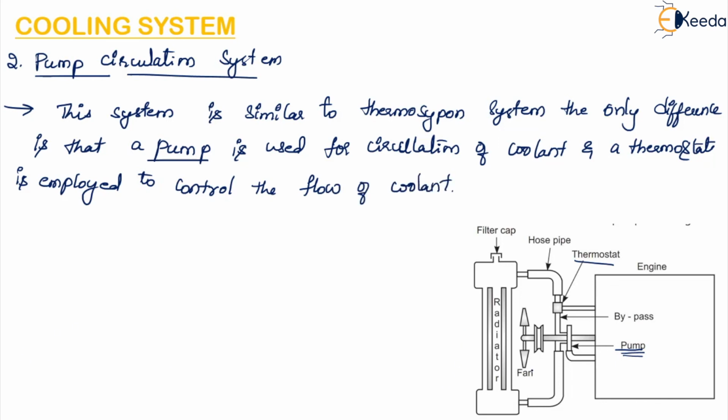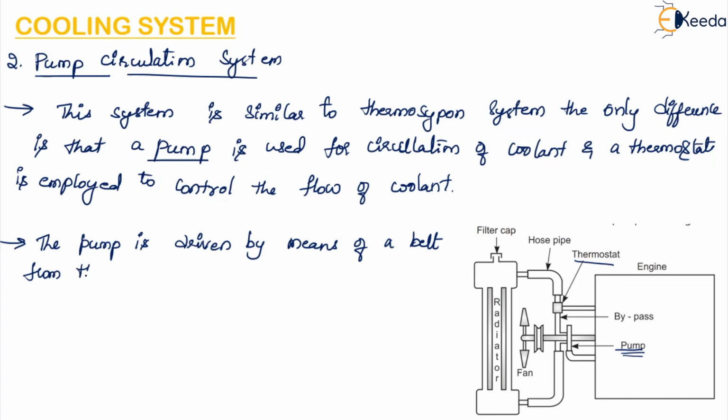So how is this pump driven? The pump is driven by means of a belt from the engine's crankshaft. The fan which is present here behind the radiator is also driven by the same belt that drives the pump and the generator.